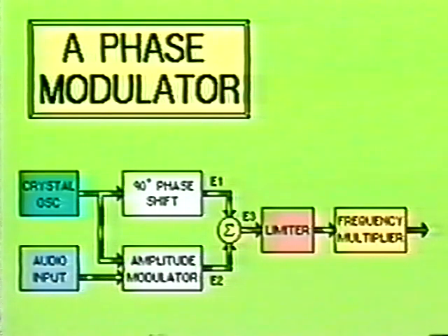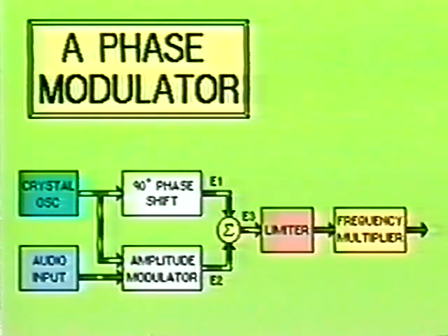Generally, the phase shift between the reference signal and the modulator signal is held between plus or minus 15 degrees from the value of the phase angle when there is no modulation. This small phase shift is usually too small for practical applications. So the signal is generally fed into a frequency multiplier circuit to increase the phase shift and corresponding frequency change to the desired value. The frequency multiplier is usually a Class C amplifier.